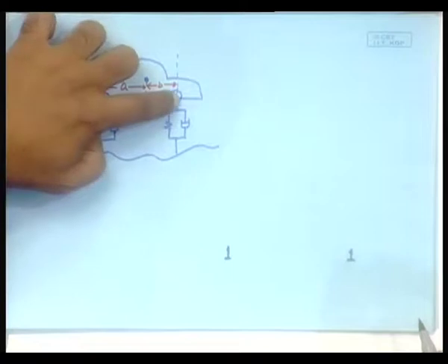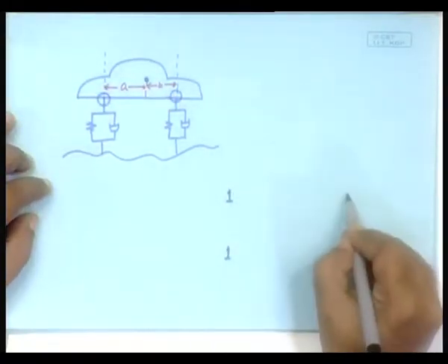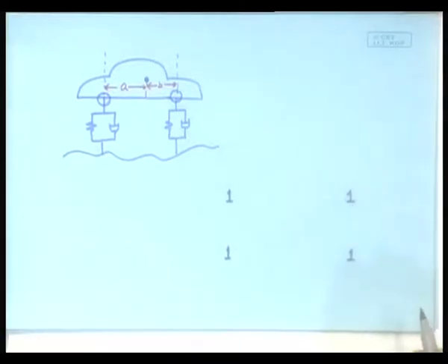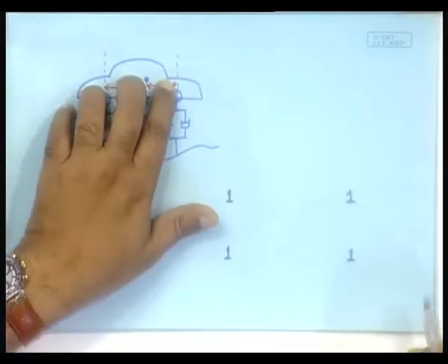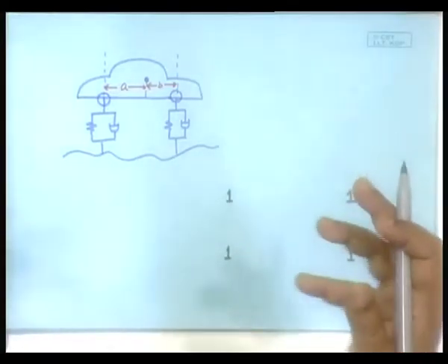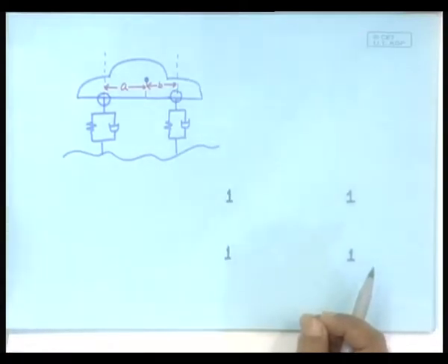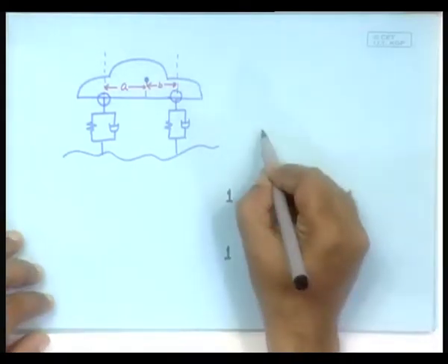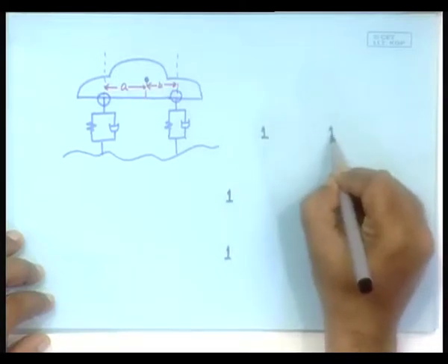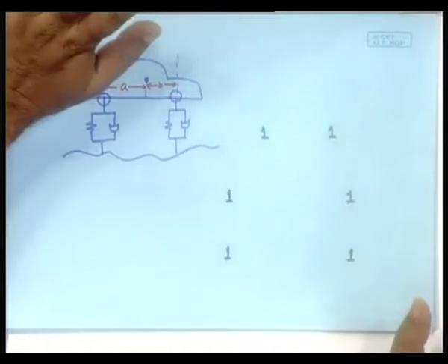These two are also the velocity points. So, one here, one here. Now, this motion, the car motion, will have two components, one the rotational component, another the translational component, and these two are also velocities, different velocities. So, for that we will put two 1 junctions like this. We will see what we can do with it, but we can identify there will be 1 junctions, right.